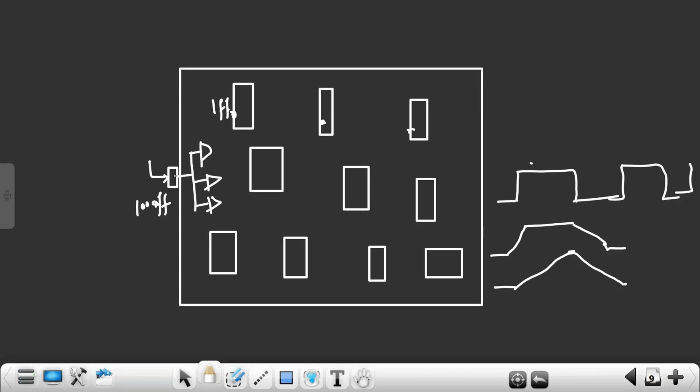So this port is now not driving how many buffers? Only 3 buffers. Now what is the load I have? Only the load of 3 buffers. And this buffer is again driving 2 other buffers. And this buffer is connecting here, and this buffer is. So from here to here, I have more length, more net length. Net length is also having net capacitance. That will also create huge load on this buffer.